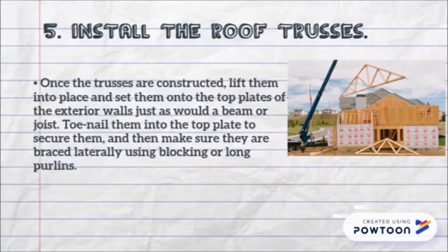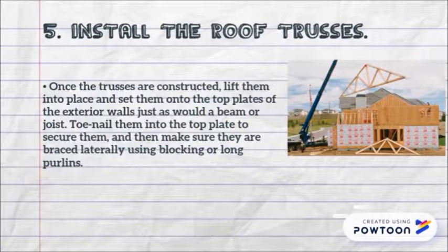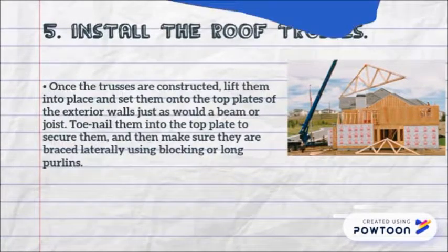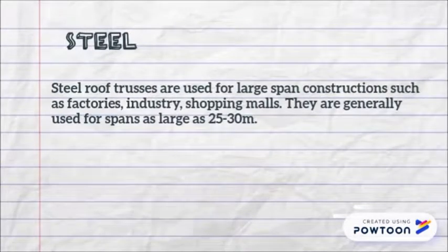Number 5. Install the roof trusses. Once the trusses are constructed, lift them into place and set them onto the top plates. Steel roof trusses are used for large-span construction such as factory, industry, shopping mall, and others.